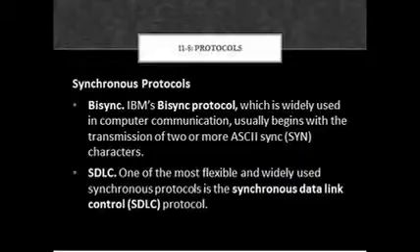A circuit for producing quadrature phase shift keying is shown in Figure 11-25. It consists of a 2-bit shift register implemented with flip-flops, commonly known as a bit splitter. The serial binary data train is shifted through its register, and the bits from the two flip-flops are applied to balanced modulators. The carrier oscillator is applied to balanced modulator 1, and through a 90-degree phase shifter to balanced modulator 2. The outputs of the balanced modulators are linearly mixed to produce the quadrature phase shift keying signal.